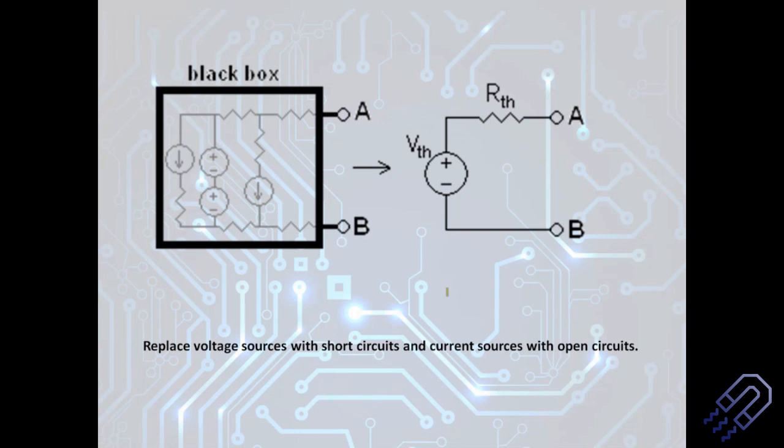If you want to find the equivalent voltage across this particular circuit, we are going to write down an equivalent voltage source, which is VTH. Then we look into all the resistances and solve them. We know about parallel and series combinations of resistance, and we are going to use those ideas to simplify the circuit and get just one equivalent resistance. That is the equivalent resistance, the Thevenin resistance.